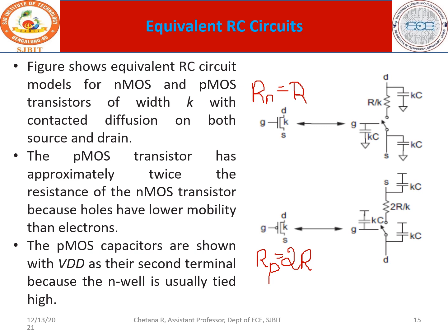Now with respect to resistance, the resistance will be divided by K, which means the resistance decreases. So whenever you have the width given with respect to an NMOS or a PMOS transistor, the resistance decreases, and that decrease is shown by R by K, and the capacitance is multiplied by that factor, which is given as Kc. So if you notice, all the capacitances are multiplied by K, whereas all the resistances are divided by K.